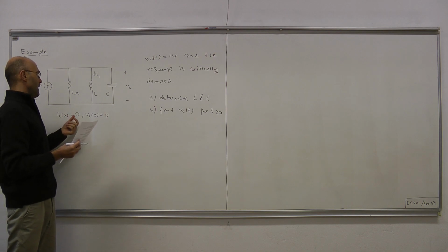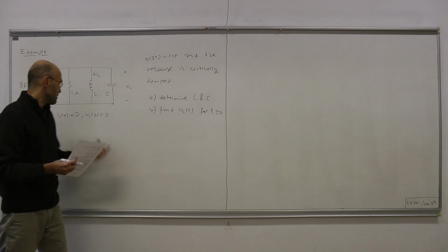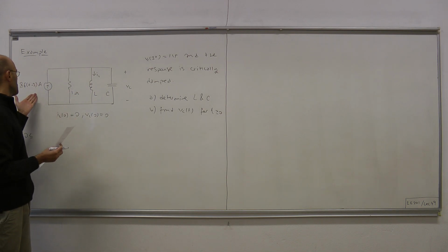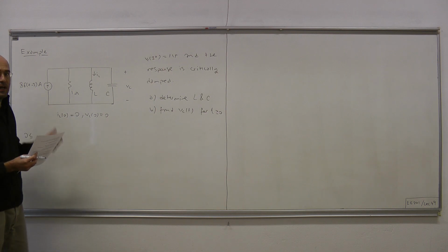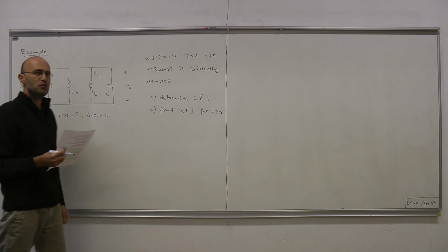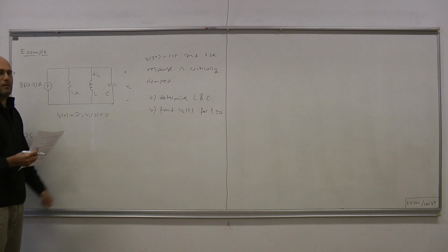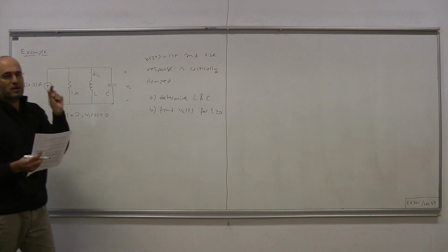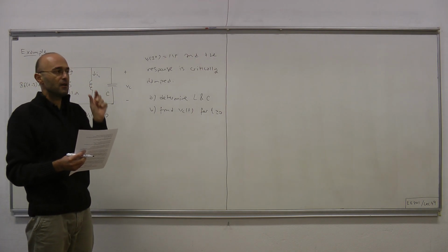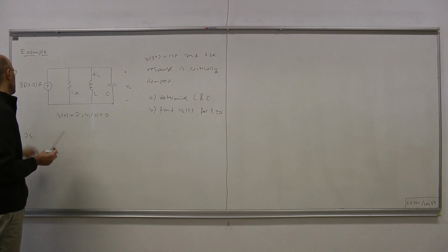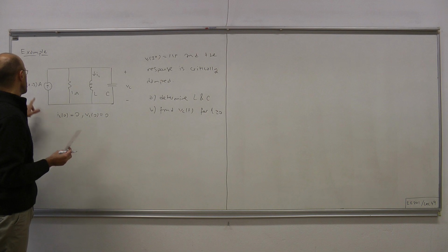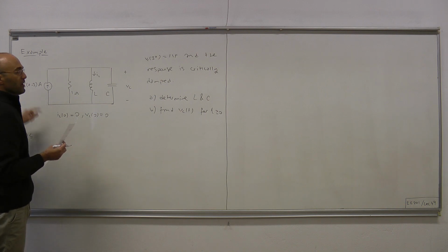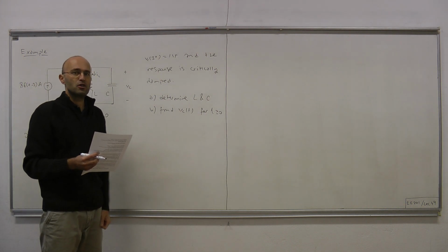And actually there's nothing to analyze there because the initial conditions are 0 and the source does nothing during that interval, so everything remains 0, for that interval from 0 to 3 minus. And then we're going to make the analysis for the infinitesimal interval from 3 minus to 3 plus. And we're going to see how the impulsive current source changes the initial conditions.